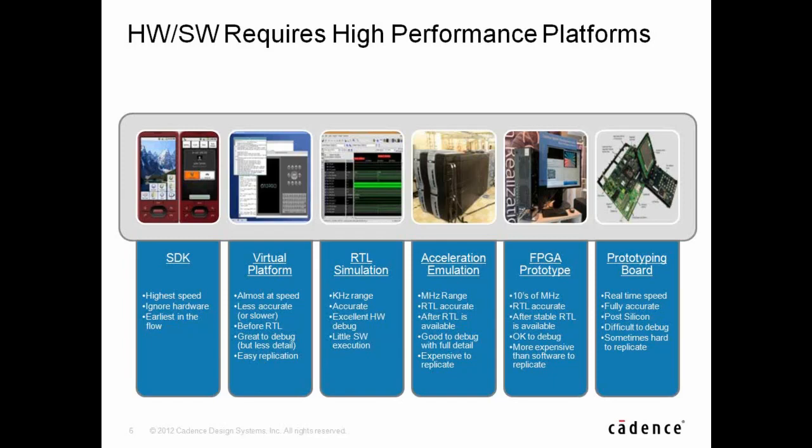There's obviously a debug aspect for the software, which is completely orthogonal to the debug for the hardware. So how does that look when we start to get to Palladium and FPGA, maybe even post-silicon? What do we put in post-silicon so that if we find a bug here, how do we replicate it here where we can do more debug? That's really important, right? And how do we find, if we find a bug here, can we move it to here where we've got even more capabilities? You know, your VIP will run here with comprehensive protocol checkers, coverage, all sorts of good stuff. It won't necessarily run here, right?